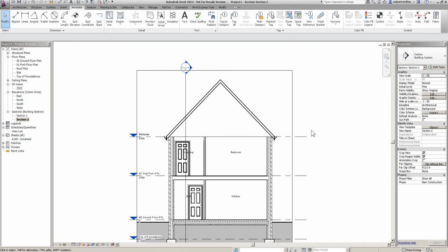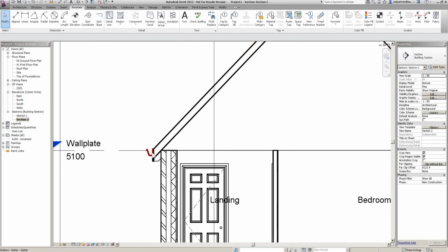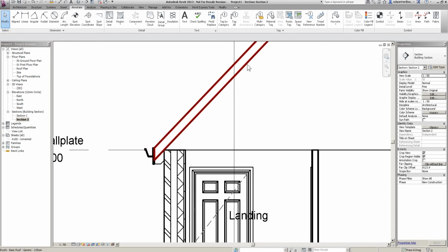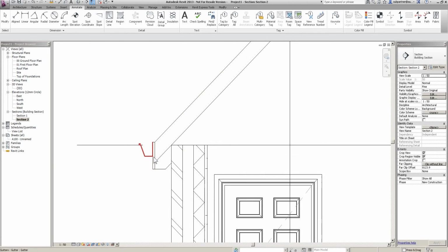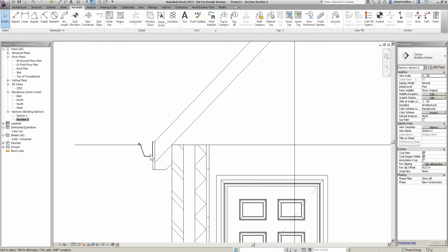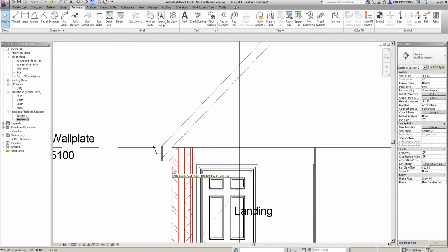Now, while I'm just here, I'm going to show you very quickly why I don't use a full build-up of roof all the time. Now, I'm just going to put thin line mode on a second, just to show you how this will look. Okay, it's not for detail. I basically treat this roof construction like the rafters. Whether we're using trusses or not is beside the point. Just as rafters, just for now.